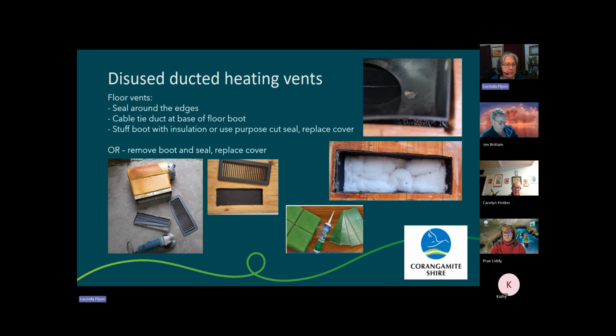Disused ducted heating vents, we already talked about those gaps in the sides. I don't know if you can see that, but you can see gravel under the house through that one. So generally, there's two things. If you're going to keep your gas ducted system, then all you do is seal those edges. But if you're going to decommission it, unless you're going to change your flooring or your carpet or your timber, it's really hard to make it look as though they weren't there. So most people will just stuff some insulation in them and put the cover back on.